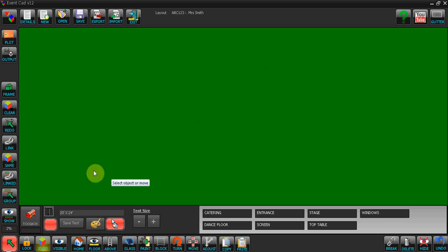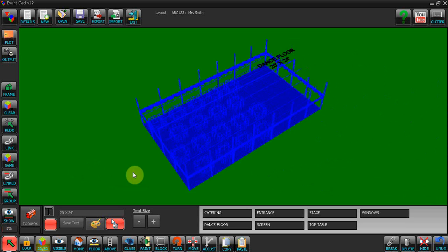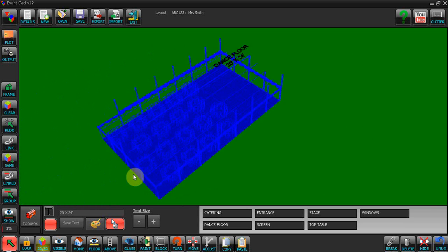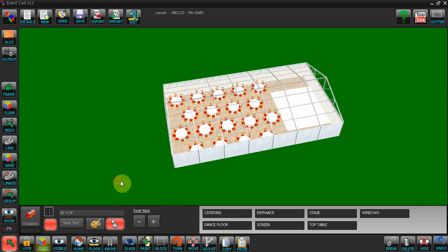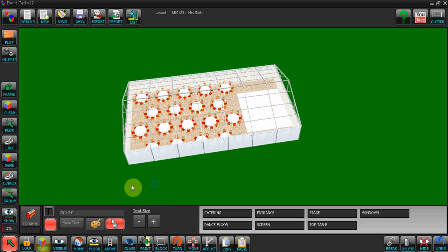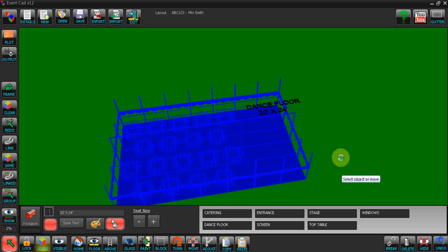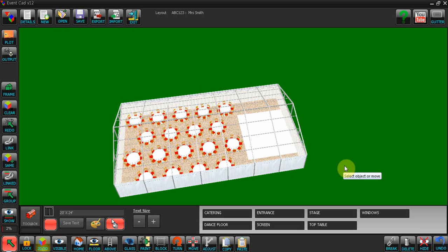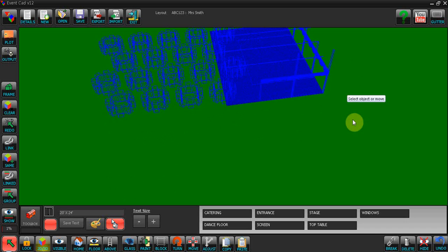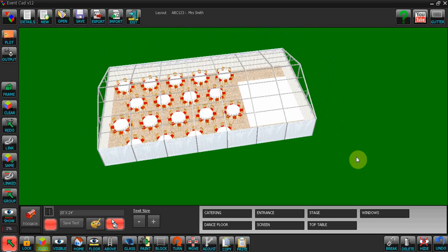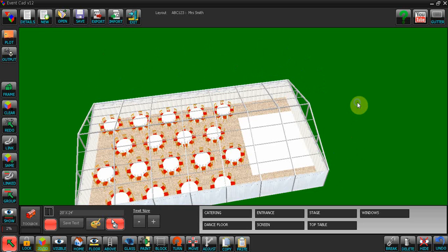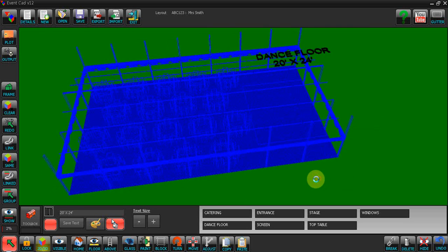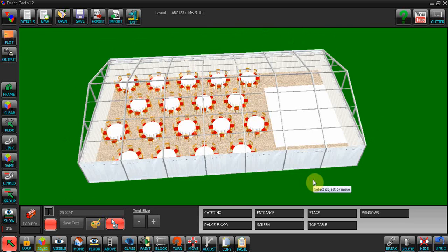If you do the same with the left mouse button, you'll see that the centre of rotation is much wider, and usually a combination of the two will get you to a good position. To go closer to the tent, use the left mouse and go forward, backwards to zoom out, and to come down from the aerial view that we're at the moment, right mouse and down, or up if you need to go further up. So left mouse and forward, right mouse and down, left mouse and turn it around a little bit. That gives us quite a nice view.